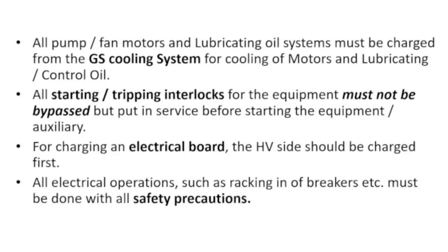All starting and tripping interlocks for the equipment must not be bypassed but put in service before starting the equipment or the auxiliary. For charging an electrical board, the high voltage side should be charged first. All electrical operations such as raking in of the breakers etc. must be done with all safety precautions.